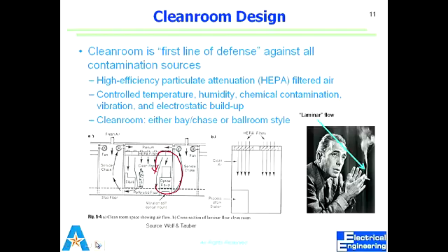So we look at those, we check for vibration in the clean room, we check for electrostatic buildup. Why would vibration be important to monitor in a clean room? Exposure? 4,000 RPM. Where do we do 4,000 RPM? We rotate things at high speeds. Spinning for photoresist application, right? I gave you that example. So you don't need vibrations here, right? What happens if you are spinning something at such high RPM and you have vibration?